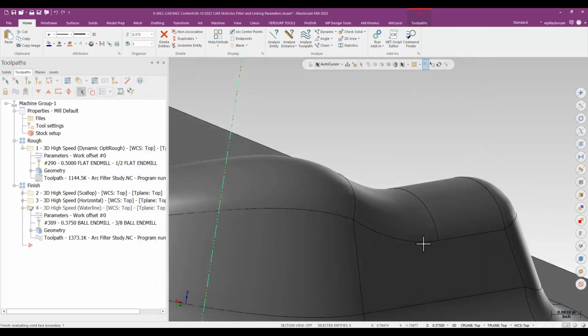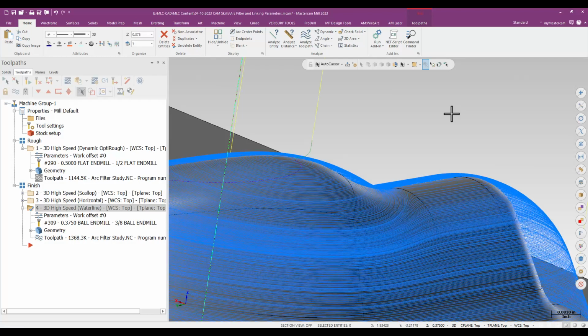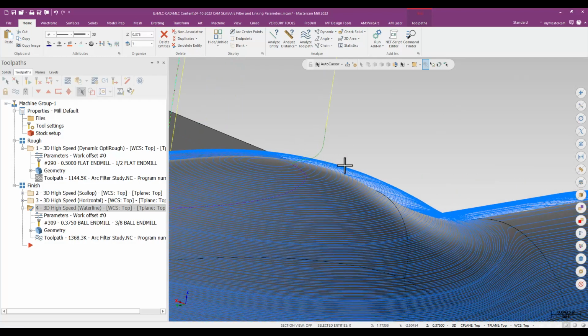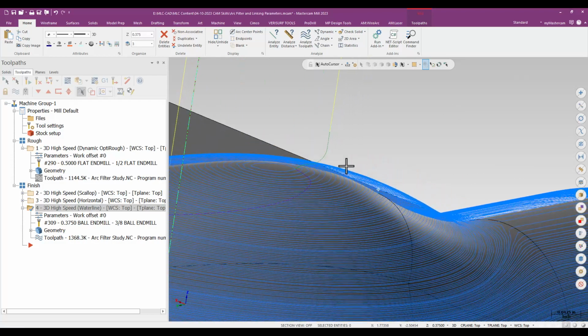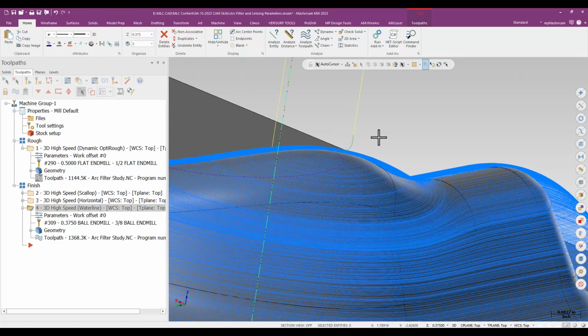And then hopefully what I see when that regenerates, we might have to wait a second for this one. It's got a lot of passes. I just see that entry and exit be that little bit smaller. And anytime I can find a chance to shorten some of those travel times out of a part, entry and exits are a good place. Retract heights are a good way to do it. Hopefully, I'm just increasing overall the efficiency of how that toolpath's going to work.